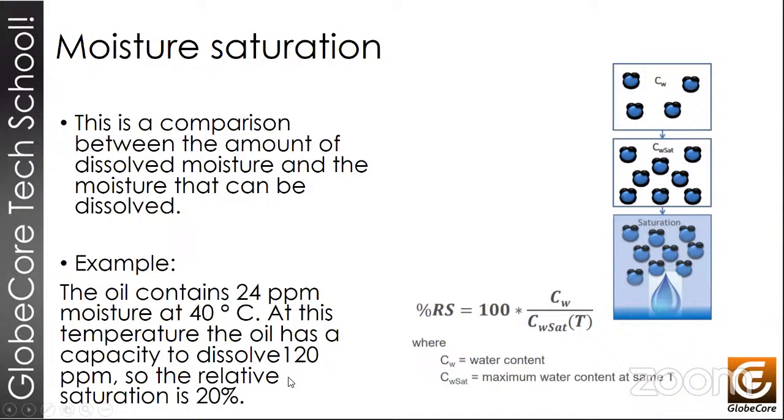Of course, the actual numbers of water content are small, so we're talking about something like differences of parts per million. So this characteristic is seriously affected by temperature. And for this reason, it's very important to know the temperature of the sample that we take at the time of sampling, or at least to have equipment that can provide these values.